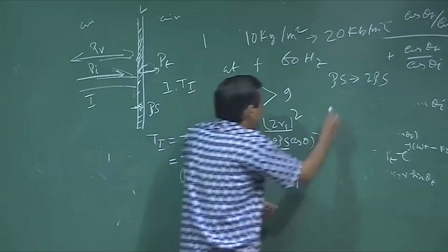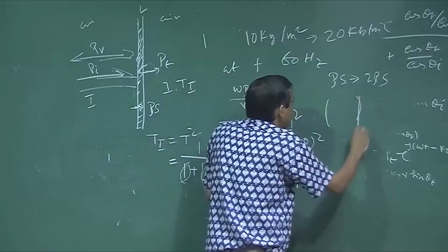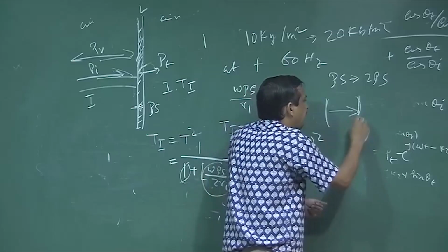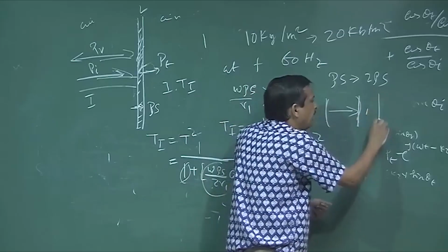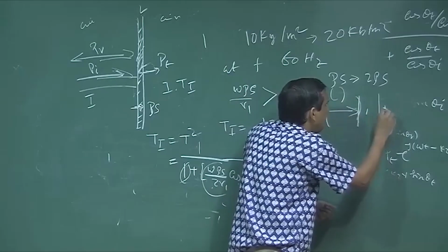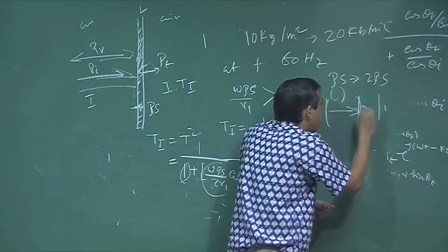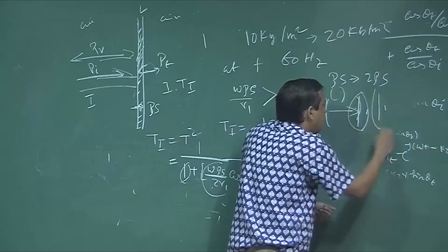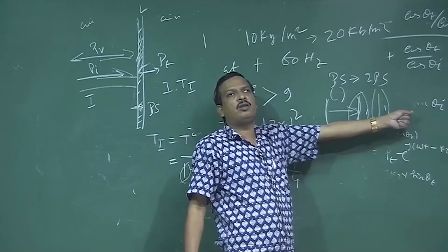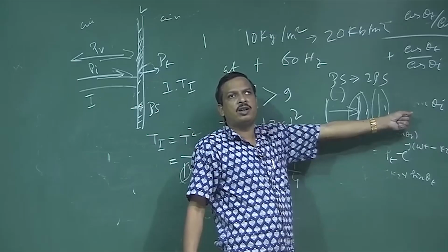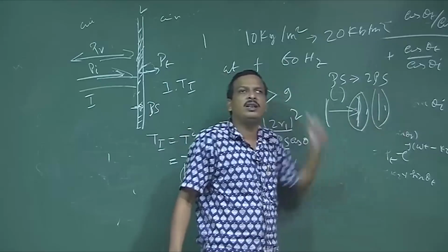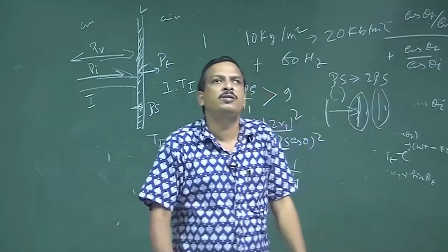So, first, this is a studio, and this is a glass door in one layer. So, the mass law is calculated. If it is glass, then there is air, and again I have a glass, then the outside noise cannot go inside, because there will be a mass law effect in each of the two walls. So, inside that auditorium, if two separated glass doors are used, very little outside noise will enter. That is why this is mostly used in architectural acoustics.